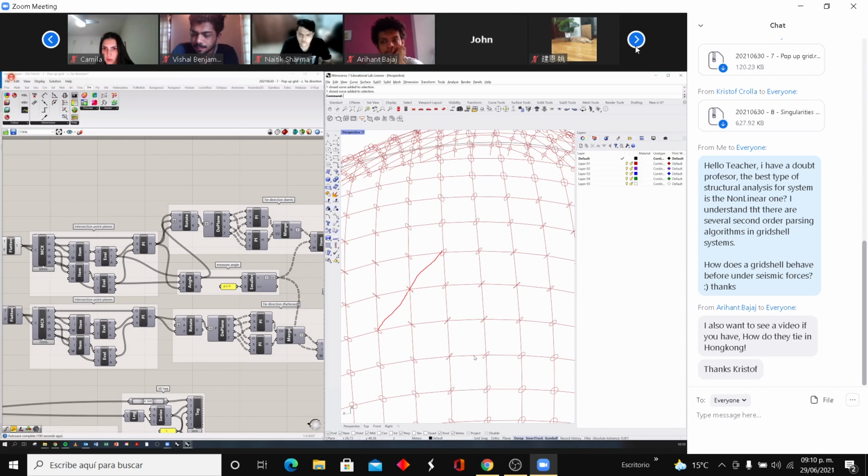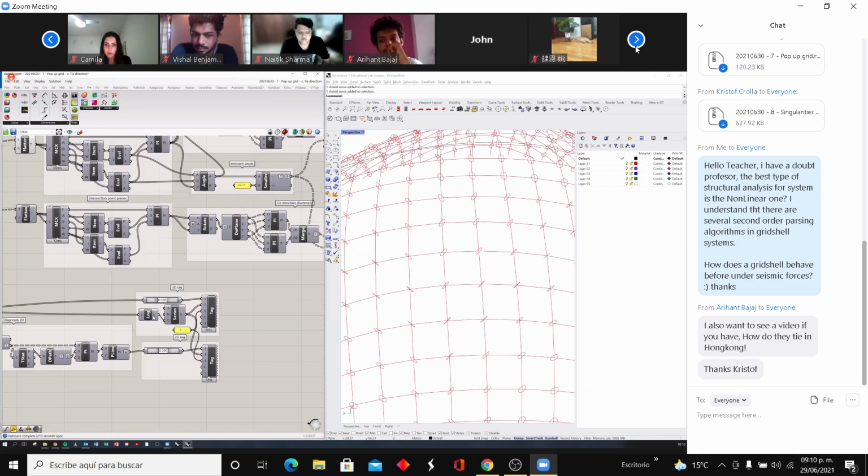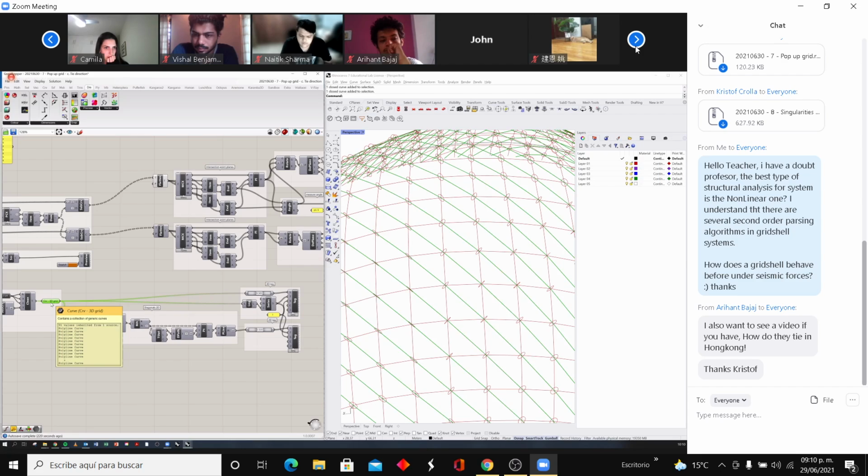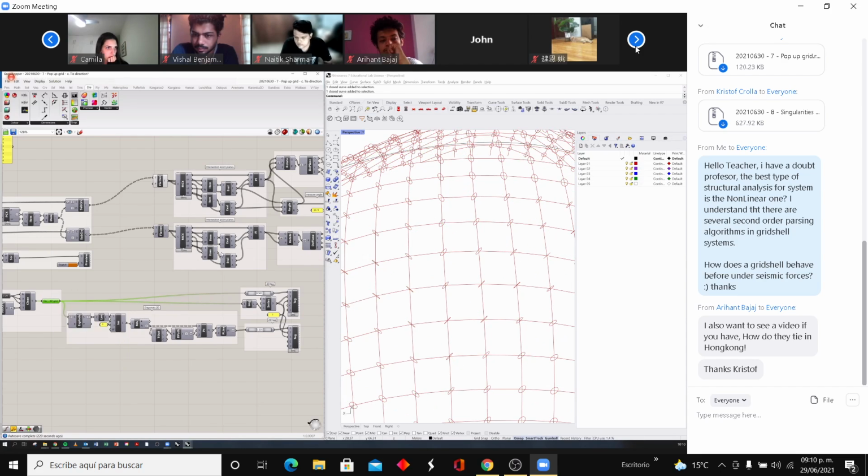Yes, it's just for the original grid, because those are the ties that deform with the whole structure as we keep on going up, and it's to prevent those from snapping. If a 90-degree angle becomes very tight, it can either break the bamboo if it's metal wire, or it can snap the tie if it's plastic. So it has nothing to do with the diagonal direction. No, this is the first knot that we have. And then on top of that, we can add whichever diagonal we want to have. But that's totally separate from it. Okay.